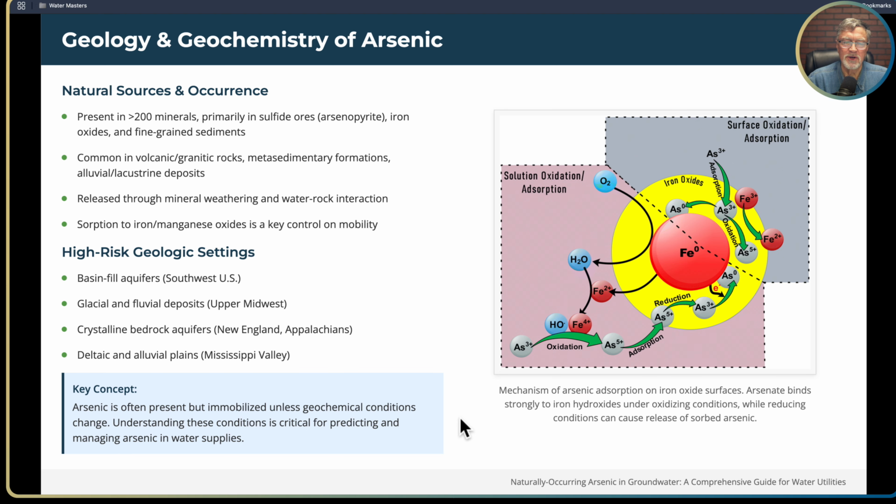If your high production zones are also high arsenic zones, then you're probably going to have to take the water and deal with it. But we can balance those things out usually. But doing enough vertical profiling so you understand the profile of the arsenic and how it relates to the geology, and then specifically design the well to minimize and seal off those zones that have high arsenic can go a long way towards reducing the arsenic concentrations in your well.